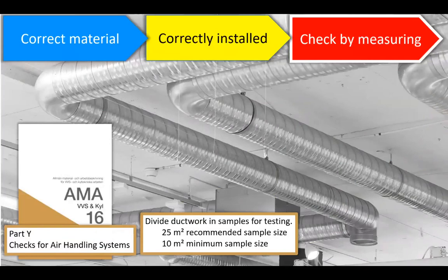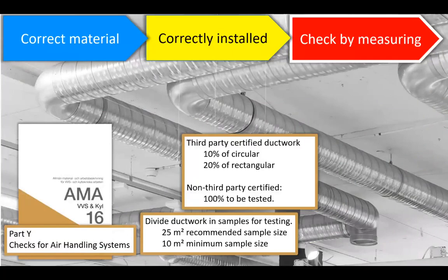Oh, thanks. I'm lucky. My system is certified, and I can read in the standards how to carry out the testing. Just one more question. What's the test pressure? You shall measure the leakage at the duty pressure of your system, but not lower than 200 Pascal. If you don't know the duty pressure, you shall test it at 400 Pascal.